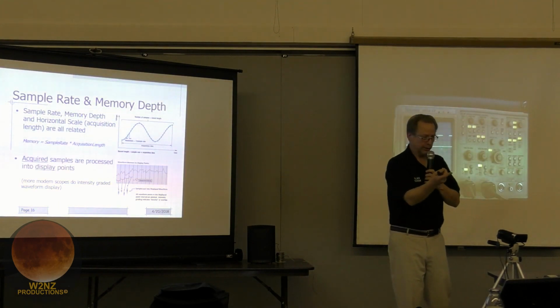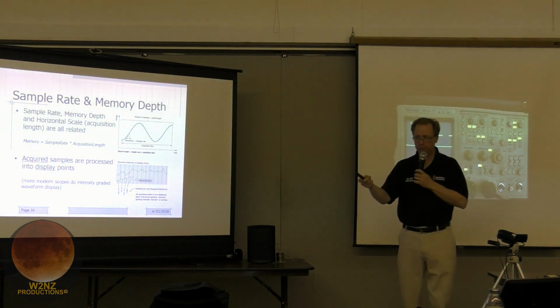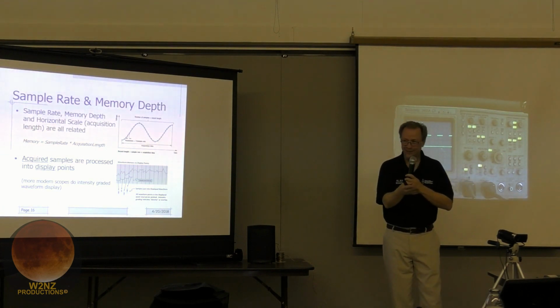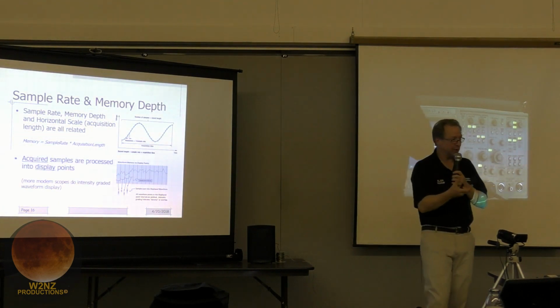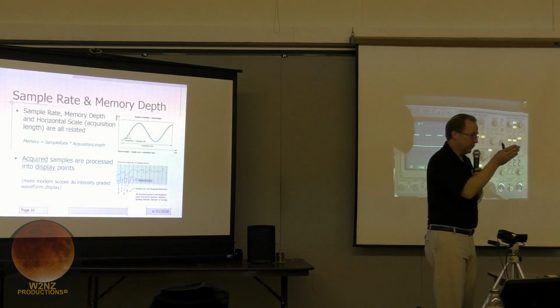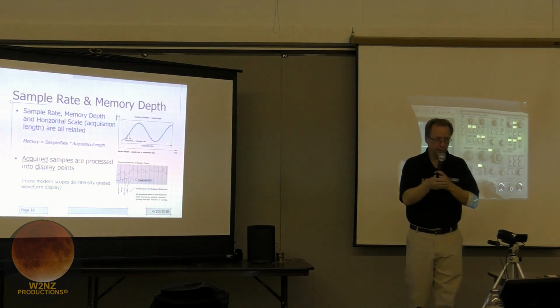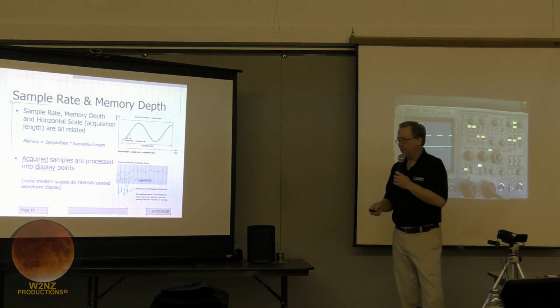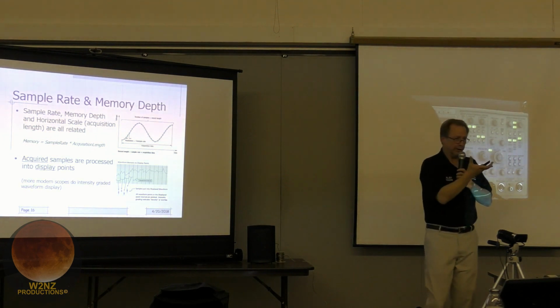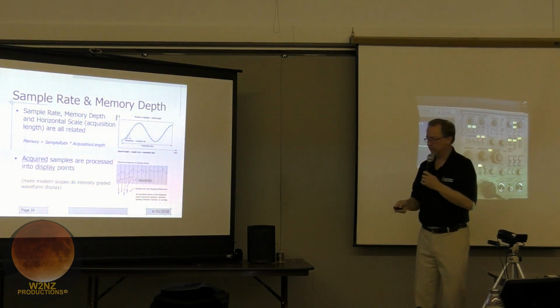When I'm demonstrating a digital scope to people, I still call it sweep speed, even though there's no sweep in the digital scopes. But it's still the same concept. It's still so many nanoseconds, microseconds, picoseconds, whatever, per division. But at the end of the day, it really is an acquisition length of what we're putting in memory.